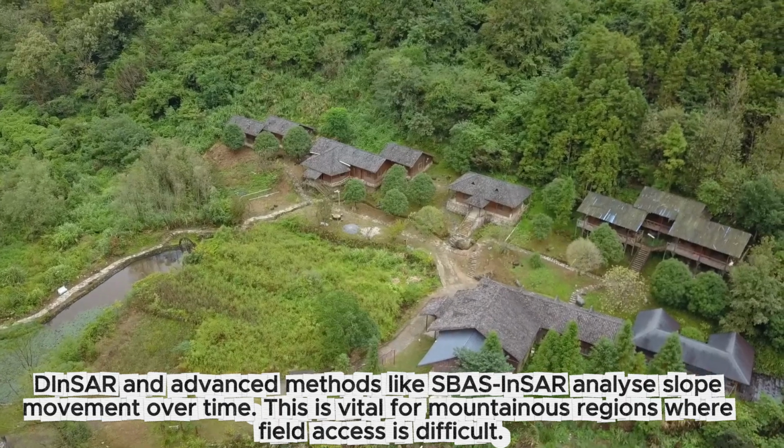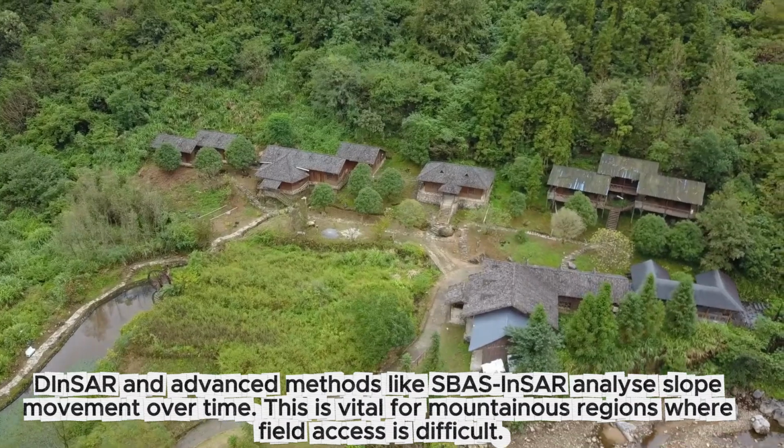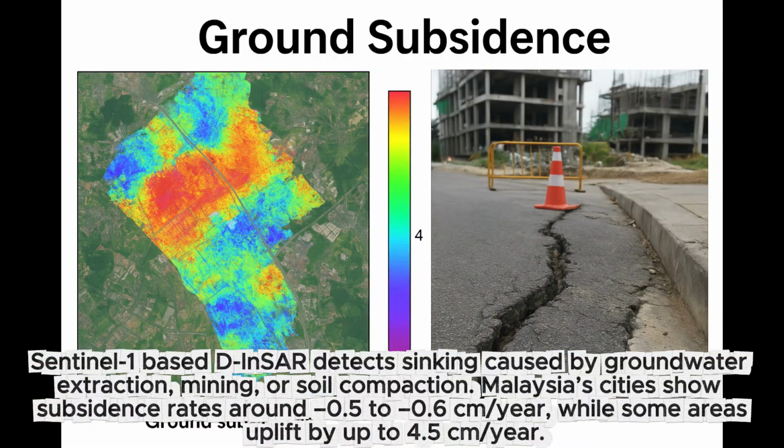InSAR and advanced methods like SBAS InSAR analyze slope movement over time. This is vital for mountainous regions where field access is difficult. Sentinel-1 based InSAR detects sinking caused by groundwater extraction, mining, or soil compaction. Malaysia's cities show subsidence rates around -0.5 to -0.6 centimeters per year, while some areas uplift by up to 4.5 centimeters per year.